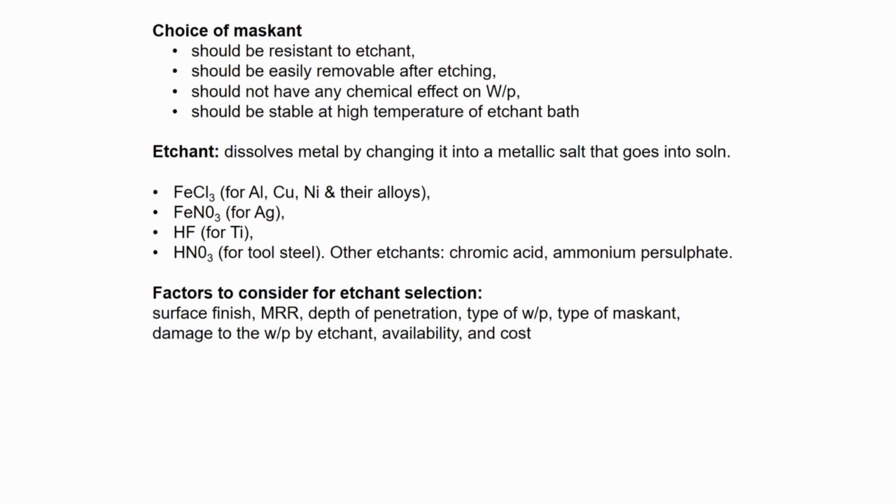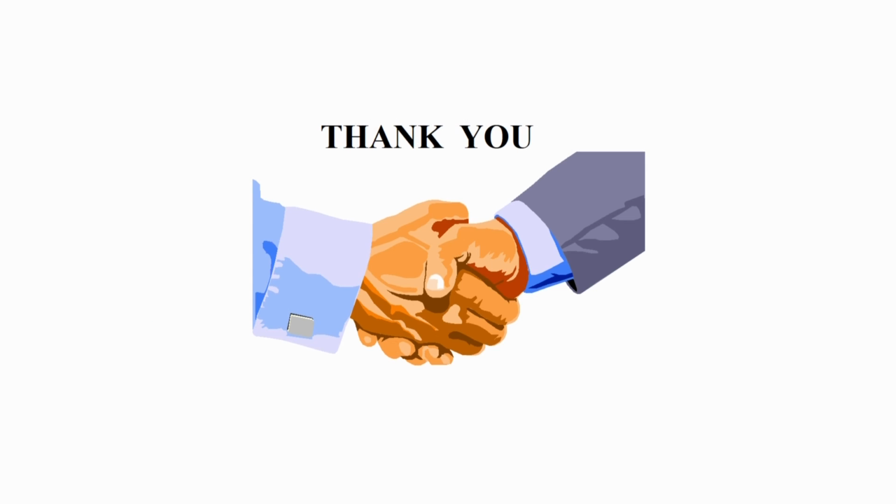So the factors to consider during etchant selection: surface finish, material removal rate, how much material removal rate is required, depth of penetration, type of workpiece, type of maskant, damage to the workpiece by the etchant, and availability and cost also matter while selecting the etchant.